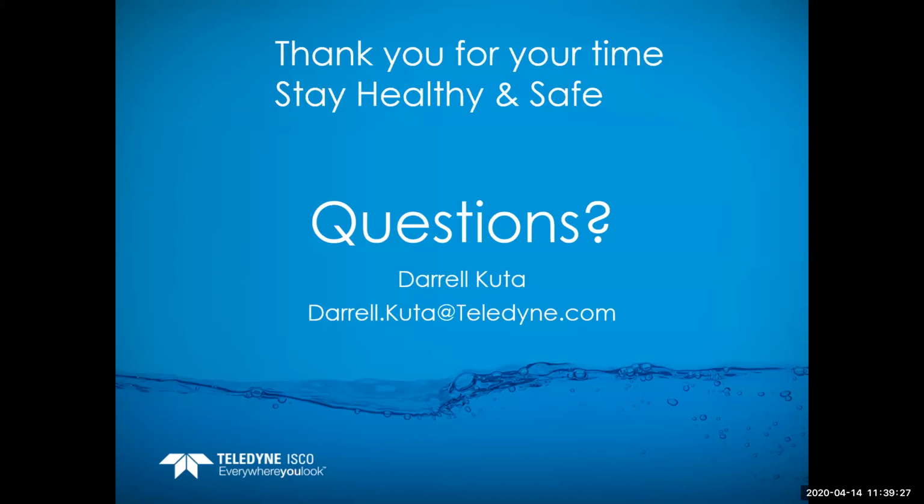Let's see, would you choose the pressure sensor to start a composite sampler in a manhole? Sure, you could use a pressure transducer to start a sampler. So you can do two things with it. One, you could trigger your sampler just on depth. Like if it's an ISCO sampler, you can tell it that my water depth is greater than 6 inches, and it can start the sampler program. And then you could also use it to calculate flow through that channel. So you could start it on depth, and then you could flow pace your sampler after that.